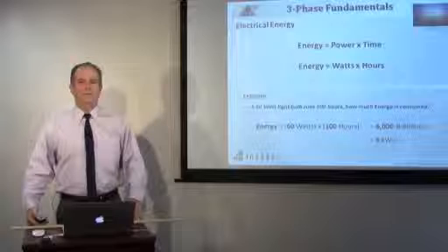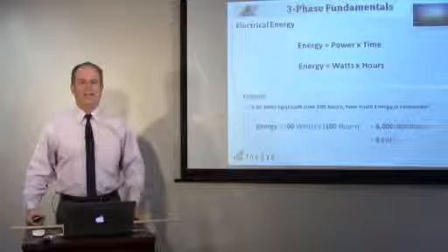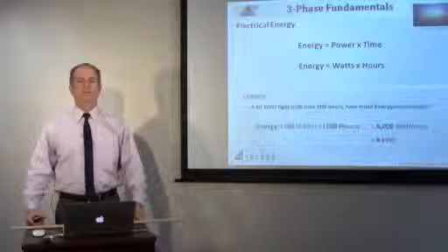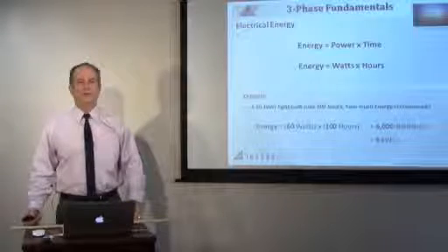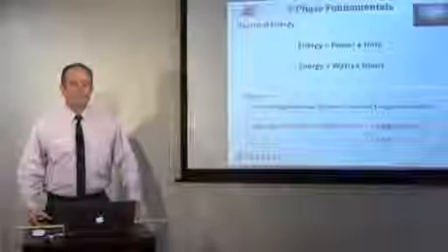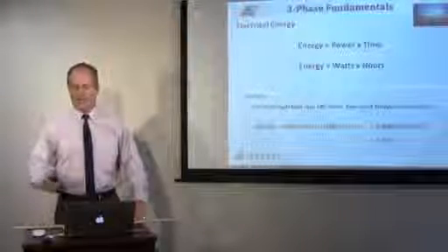The factor of square root of 3 does not come into play here when we're talking energy. This happens to be a single-phase load. If you were to use a three-phase load, then there would be a factor of square root of 3 in there.